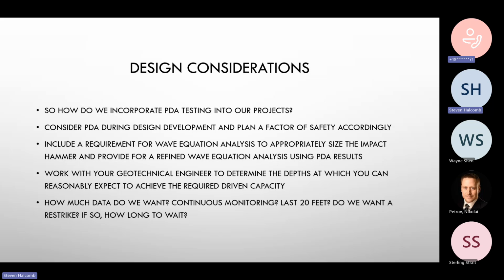And then think about, are you doing continuous monitoring? Do you want to do the last little bit? Usually the last 20 feet or so is a decent amount. When I was taught how to pile drive by Keith Corey, the former foundation engineer, Keith emphasized that he didn't care about the upper 40 feet or whatever it was. But as we got to our bearing layers and things, we became more interested. So you think about that in terms of planning the PDA and the design, in terms of how much data do you want? And then any restrikes if you think you're going to want them.